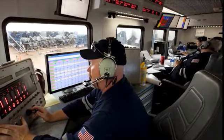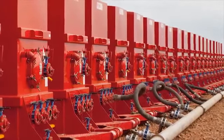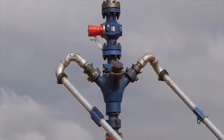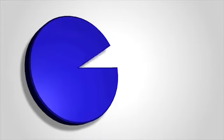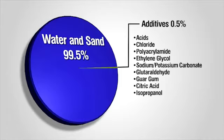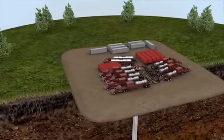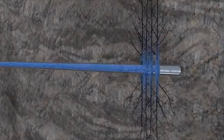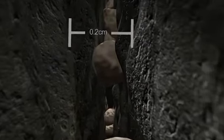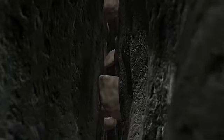The process consists of pumping a mixture of mostly water and sand, plus a few chemicals, under controlled conditions into deep underground reservoir formations. The chemicals are generally for lubrication, to keep bacteria from forming, and to help carry the sand. These chemicals typically range in concentrations from 0.1 to 0.5% by volume and help to improve the performance of the stimulation. This stimulation fluid is sent to trucks that pump the fluid into the wellbore and out through the perforations that were noted earlier. This process creates fractures in the oil and gas reservoir rock. The sand in the frac fluid remains in these fractures in the rock and keeps them open when the pump pressure is relieved. This allows the previously trapped oil or natural gas to flow to the wellbore more easily.